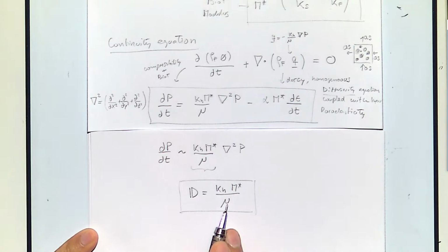If the solid has a very small viscosity, also is going to drain faster. A porous solid filled with a gas is going to drain a lot faster than a porous solid filled with, say, a viscous oil, and subjected to similar conditions, just because of the viscosity part. It takes more time to flow that viscous fluid throughout it.